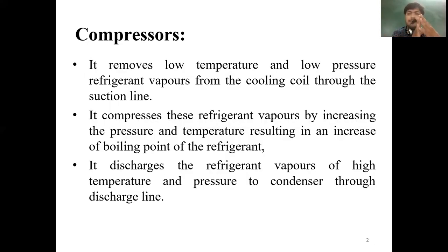As pressure increases, temperature also increases. The compressor increases the pressure of the fluid, but a compressor can handle only vapor or gas form, while a pump handles only liquid. A pump is used in a VARS cycle, and in a VCRS cycle a compressor is used.